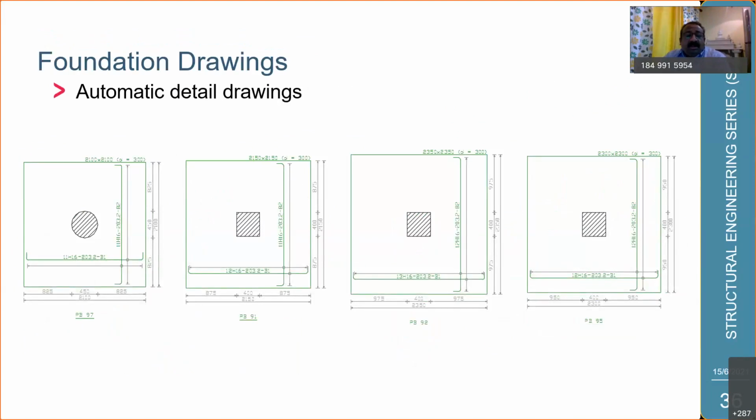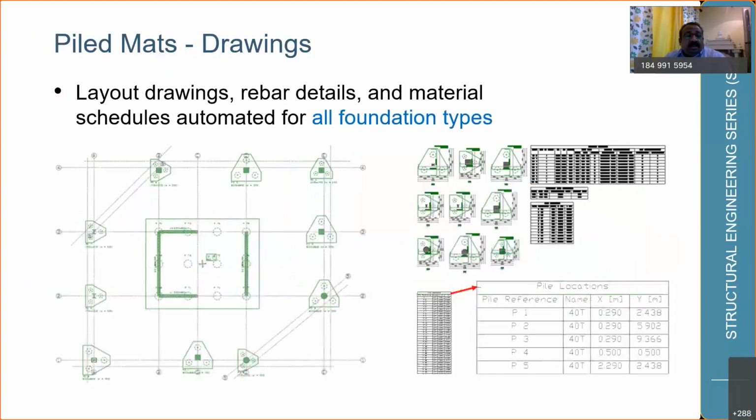One can control how many rebars you want to show in the drawings, and also control the color, the font, the size, and the positioning. All these features are readily available, so we can do it very easily. That is possible, and you can export as a CAD file. And even the layout drawings, the rebar details and the material schedules are automated for all foundation types.